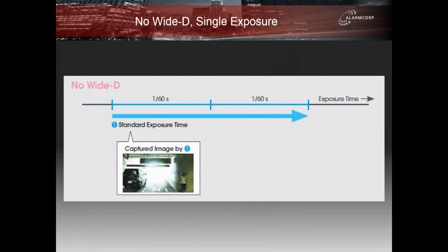The second is multi-frame imaging. The camera captures multiple versions of the field of view with each frame at a different contrast ratio. The camera combines the frames to eliminate the darkest and brightest portion of the field of view, producing the WDR frame. Of the two solutions, multi-frame imaging is the most widely used for WDR applications because it is more suitable for capturing images in real time and can process moving objects more quickly.